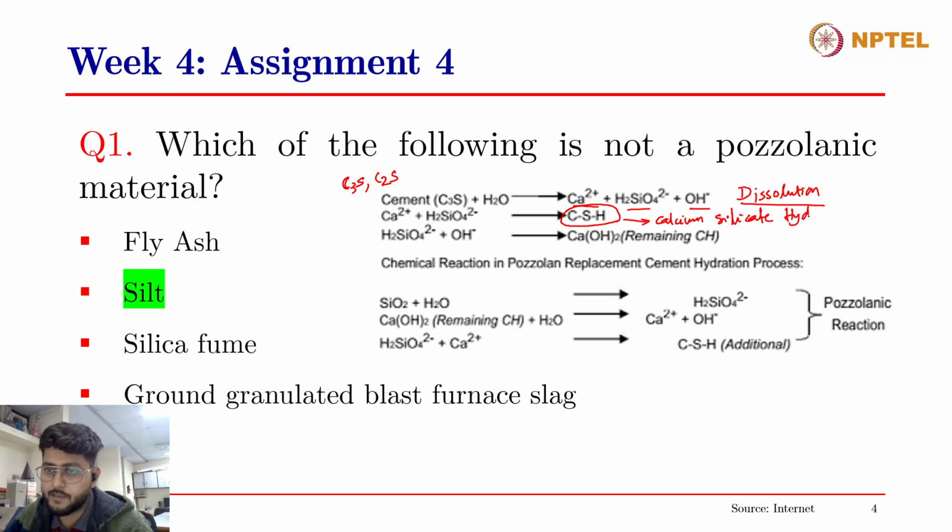And this silicate hydration product is responsible for most of the hardened strength that we get in the concrete, right? Along with the production of CSH, or calcium silicate hydrate, in this reaction, there is another byproduct that we get that is known as portlandite or calcium hydroxide, right?